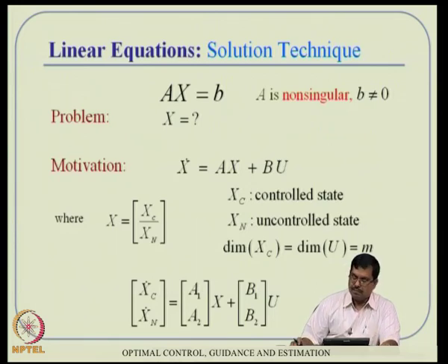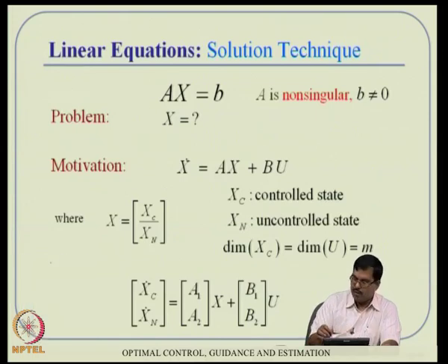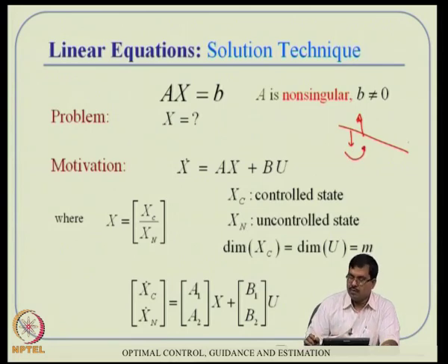That means there is a continuous gravity related, aerodynamic lift related moment which will act on the vehicle. If I show that in a small diagram, your CG will be somewhere here and CP is somewhere there. So, this will give us some sort of a turning moment, and you want to cancel that by using an equivalent moment.